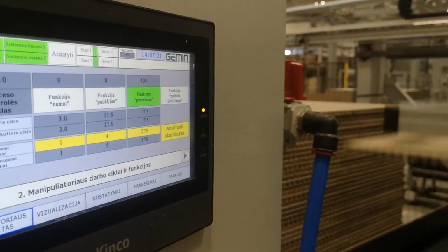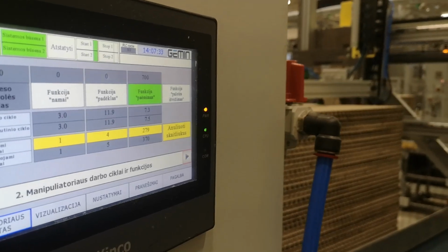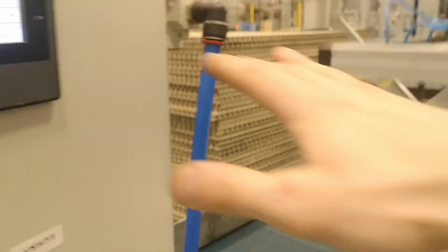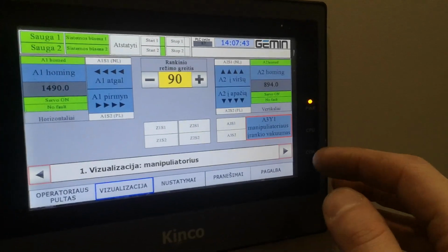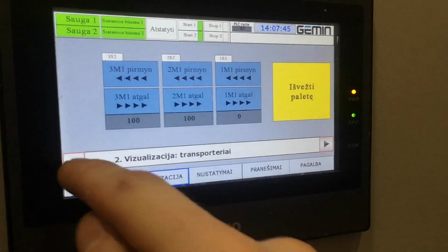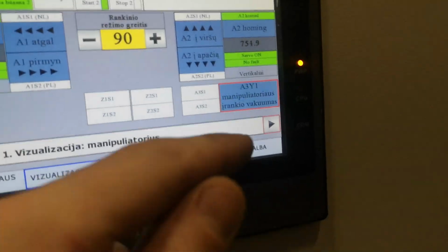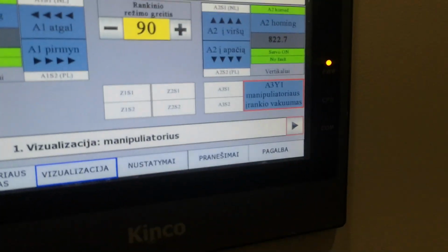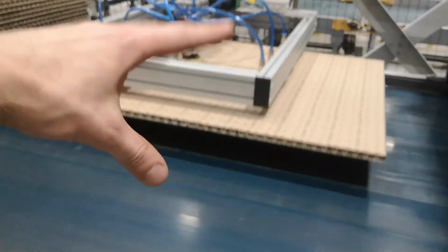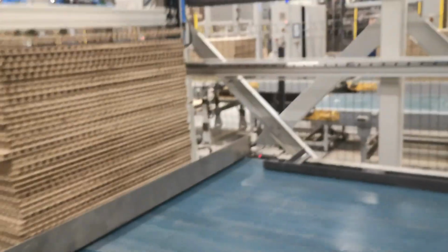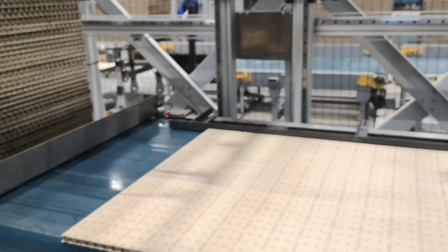Let's check. I pick up, down, pick up. So I want to add a sensor on the tool to check, when I lift up with the product, that I still have the product, because sometimes we don't grab it.